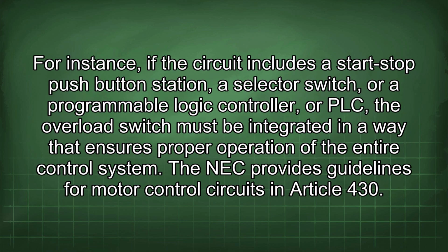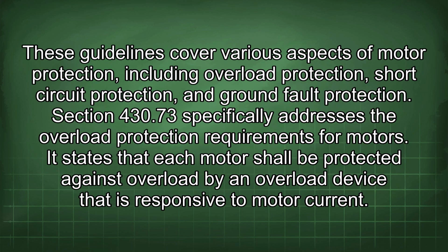For instance, if the circuit includes a start-stop push-button station, a selector switch, or a programmable logic controller, or PLC, the overload switch must be integrated in a way that ensures proper operation of the entire control system. The NEC provides guidelines for motor control circuits in Article 430. These guidelines cover various aspects of motor protection, including overload protection, short-circuit protection, and ground fault protection.